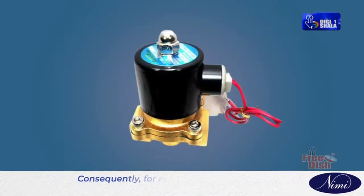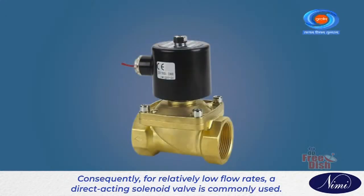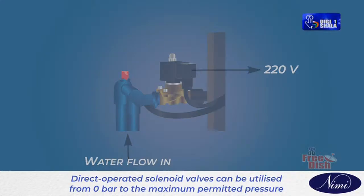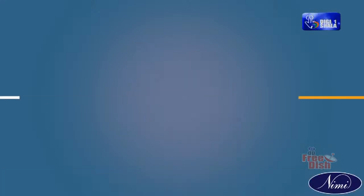flow rate. Consequently, for relatively low flow rates, a direct acting solenoid valve is commonly used. Direct operated solenoid valves can be utilized from 0 bar to the maximum permitted pressure because they have no minimum operating pressure or pressure difference requirements.